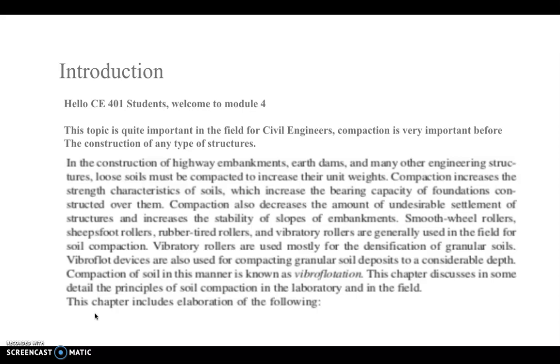So it is important because it provides the necessary flat base, which provides the crucial support for the buildings, various construction foundations, roads, pavements, and any other construction structures. So the process of compaction gives the soil higher resistance and greater stability. Usually soil is divided into two main categories, cohesive and non-cohesive soil. Therefore, the process of compaction is different depending on the type of soil.